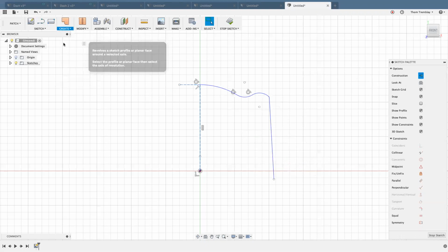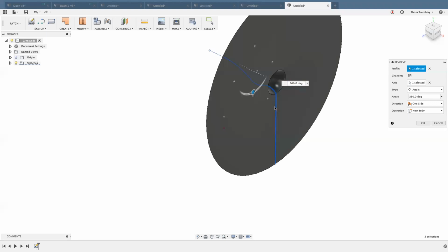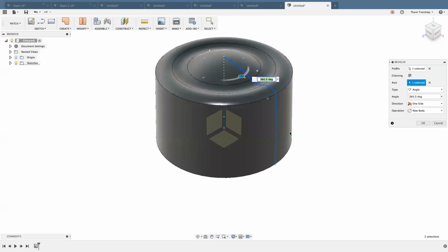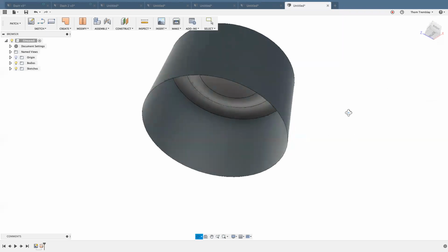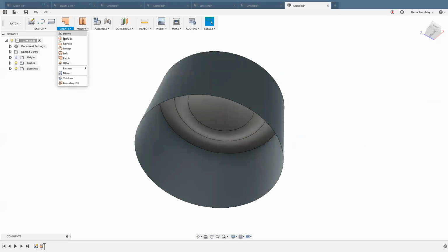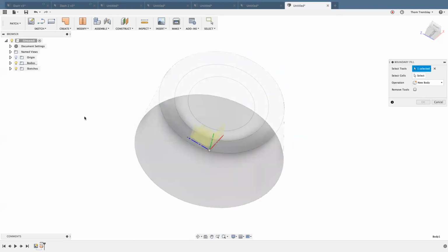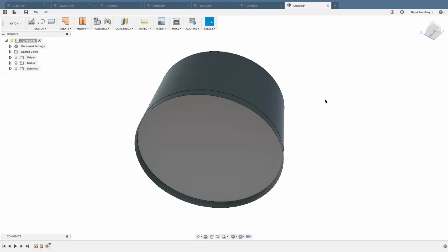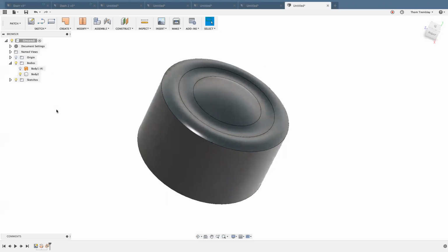Now what I want to do is revolve that profile. Let me deselect my axis. There. I'll revolve this around, and then I can use boundary fill between my revolved surface. So it's very much using a solid modeling technique and my bottom plane to create a solid model based on those bodies. Now, would it be better to use a different technique for this particular shape? Maybe just creating a solid would be better.